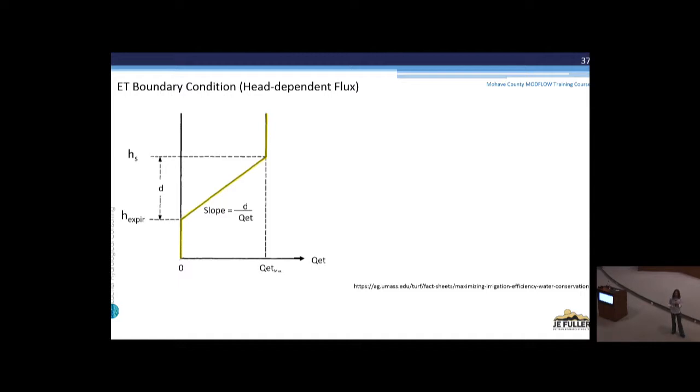They have shallow roots. They may get a little soil moisture for a few months after the stream goes away, but they're not accessing the water table. Those plants are not going to be in the groundwater model. That ET is not part of the system. That ET is subtracted out from recharge. So what you plug in as recharge in the model already accounts for those losses, okay?